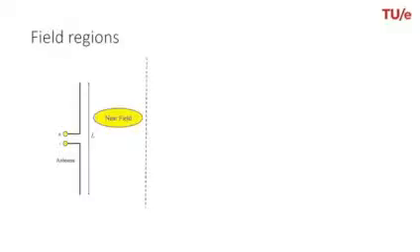If you're very far away, then of course this will not happen. Now, in between being far away and being in the near field, we have defined a Fresnel region, which is a kind of intermediate region, where we do not have the impact on the impedance anymore, but we also do not have the 1/r field dependence that we talked about earlier.